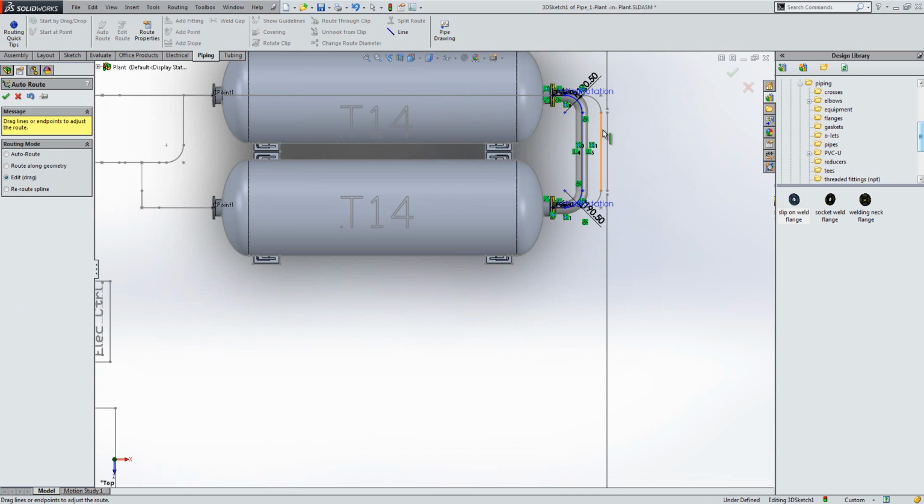And we can see that where the customer has sketched the line in and where I've got it don't match. So we can just drag this around so that they line up. Now, at the moment, I don't have any dimensions. I could go and measure the 2D sketch, for example, if I need it to be precise. But with this level of sketch, you can assume some element of guesstimation in their drawing because we haven't got as much detail as we would need for everything else. So I'm going to drag that up so it lines up with the sketch.